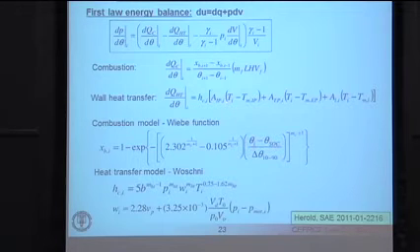We have the piston cross-sectional area, the difference in temperature between the gas and an assumed piston temperature, the head temperature and the area, and then the exposed part of the liner of the engine, the area and temperatures. So that would be a simple wall heat transfer model, but we need these convective heat transfer coefficients.